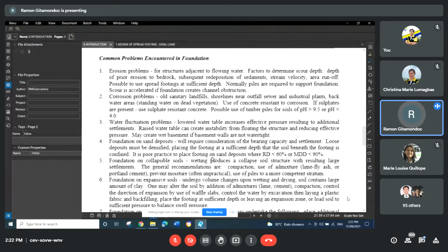The mistake that I committed was that when the soil is exposed due to the excavation, the properties will change when the soil becomes wet. So it resulted in tilting of the sheet piles, but it did not result in a total collapse. But there was really a problem as the sheet piles began to tilt.